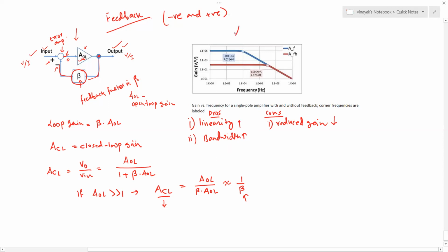So for example, look at this figure. I have a Bode plot, which is basically telling me the frequency response of an amplifier or a filter or whatever circuit I have designed using negative feedback, where the blue line is the response of a circuit without feedback, and the brown line is the response of a circuit with feedback.